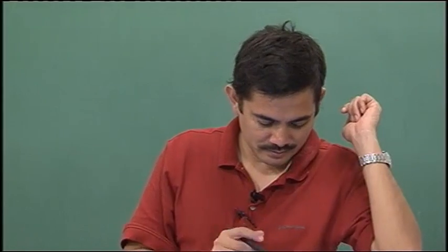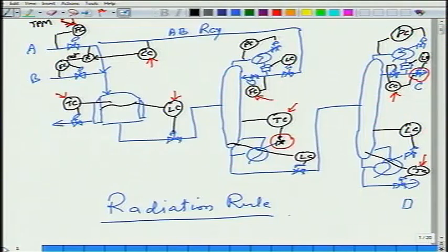So shouldn't our throughput manipulator always be at the back? No, that's not true. If I look at this control system, my throughput manipulator is at the feed. Nevertheless, the way I am managing the reflux and the reboil in my product column, if the product quality is deviating, I'll increase the reflux. If there is too much benzene coming in the product, I'll increase the temperature set point here.